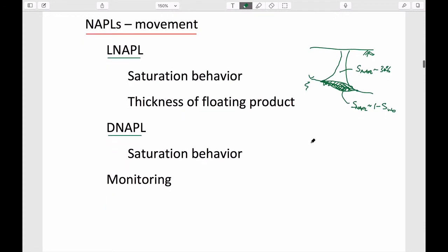And contrary to that, if we had a very similar geometry for a denser than water fluid with an underlying capillary barrier, then what we'd expect to see would be this, with exactly the same characteristics, if you like. So this again would be this partially saturated chimney that's smeared, maybe at 30% or so.